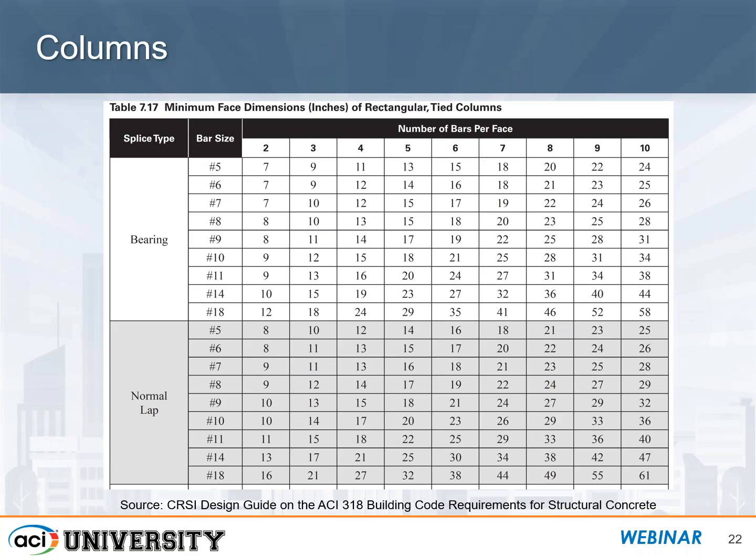Additionally, there are tables available that, for circular columns, give you the same information. What's the maximum number of bars you can fit within a certain diameter column while still satisfying all of the ACI 318 requirements for spacing. So tools that will make your life easy. You don't have to keep calculating those spacings all the time, just something to be aware of.